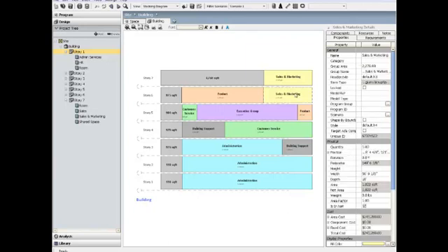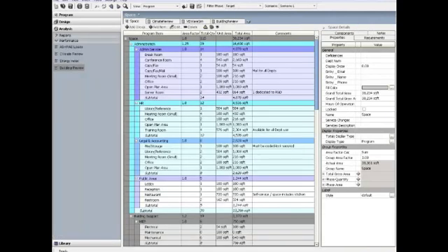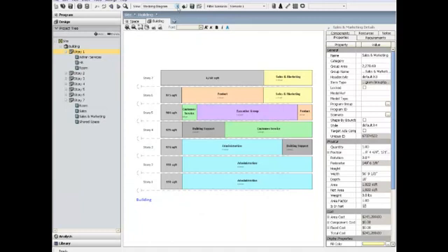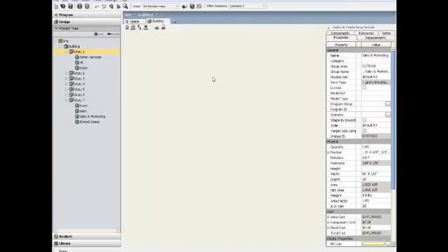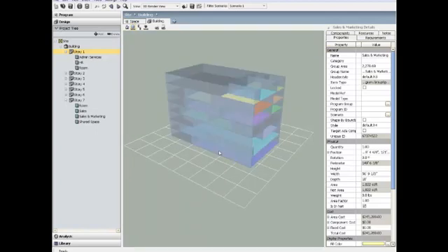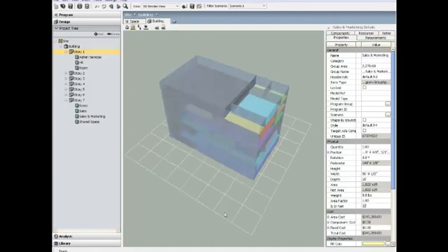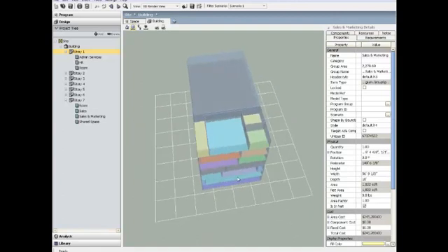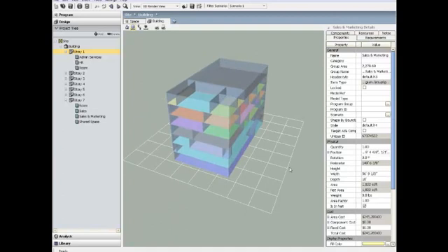In this view, the building can also be restacked by dragging and dropping departments between the different stories. To get a better idea of what the building looks like, we can also view it in 3D. The 3D view is available in the View drop-down. You can see the colors of the departments in this view as well. So here we can see it's a simple rectangular stacked building, but this will give us enough geometrical information to be able to run VE analyses.